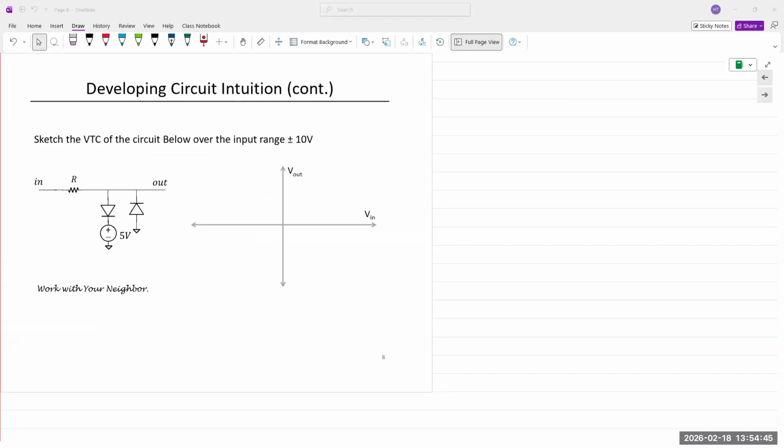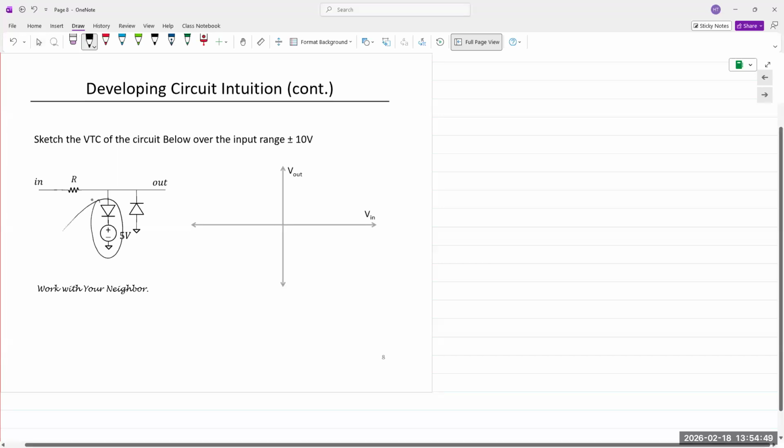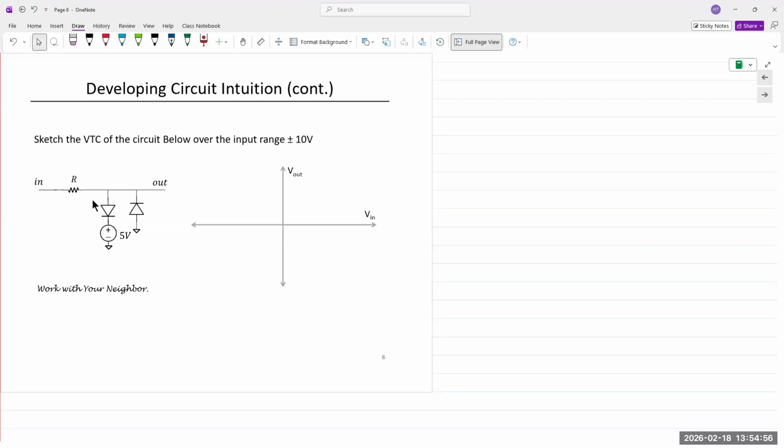You can analyze each branch independently. So we had this branch, we had already analyzed that. Now we also have another diode. The diode is facing in the opposite direction, so we'll analyze it differently. Now, if we use the CVD model with 0.7 volts, I'll go a little bit quicker because we only have a few minutes left.